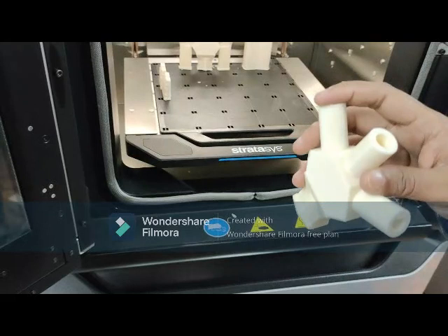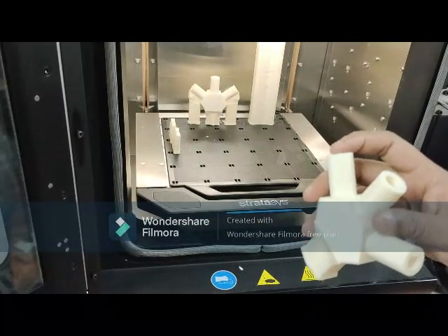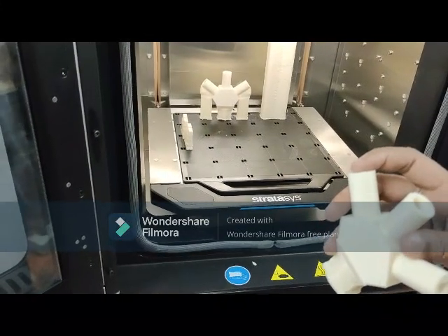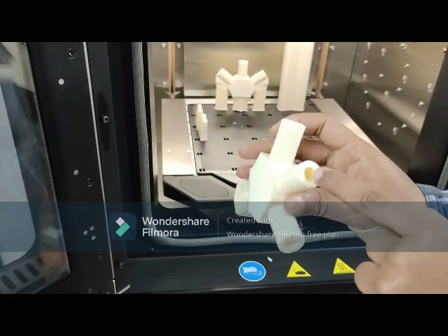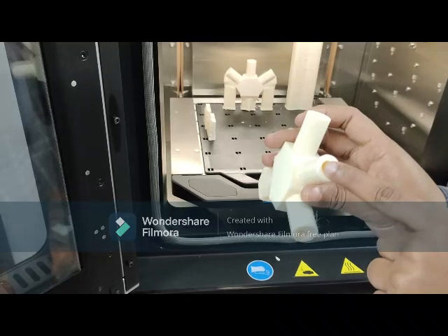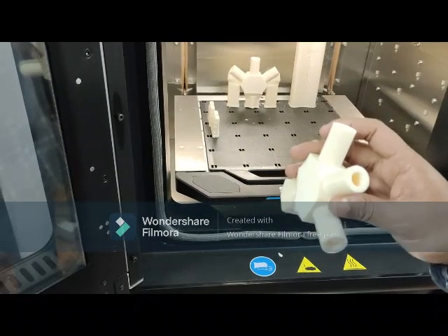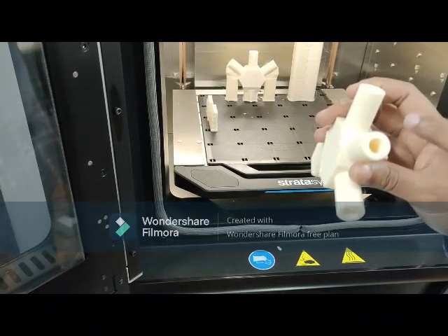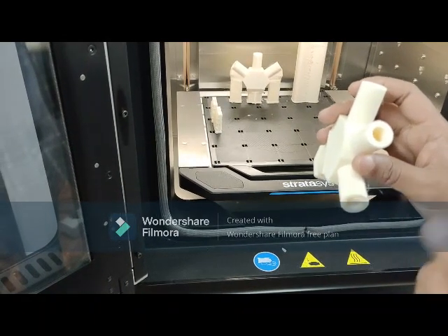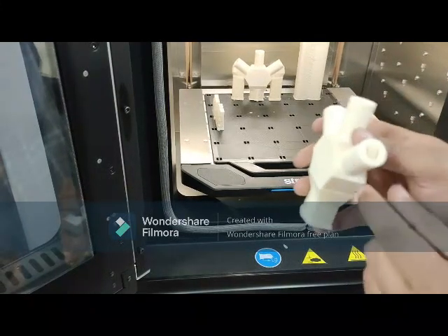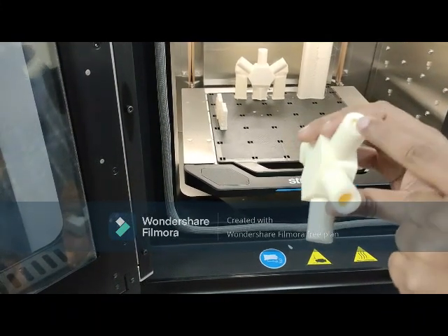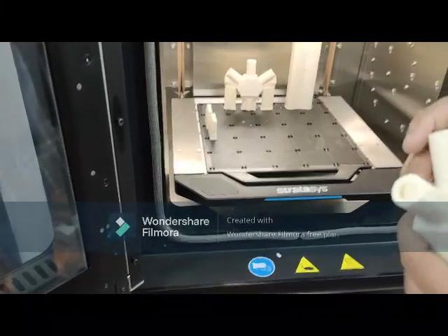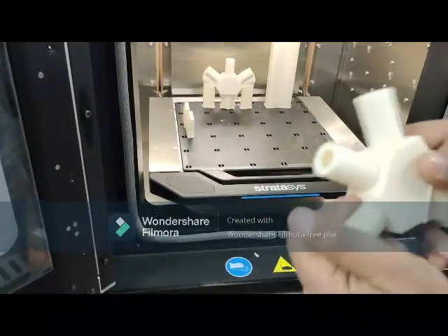We don't have the controlling power to remove support material from one section and add it to some other section. Suppose in this central section we don't have any support. All these things are controlled by the machine. We don't have the capacity to add the support material in some other location where we need it as per our necessity. We have support here, but we don't have any support material here. It is automatically given by the machine.